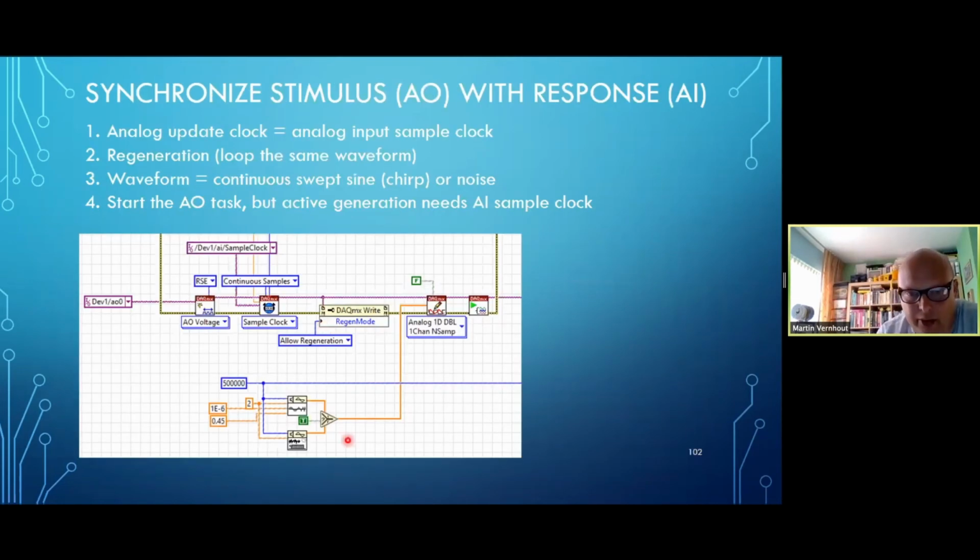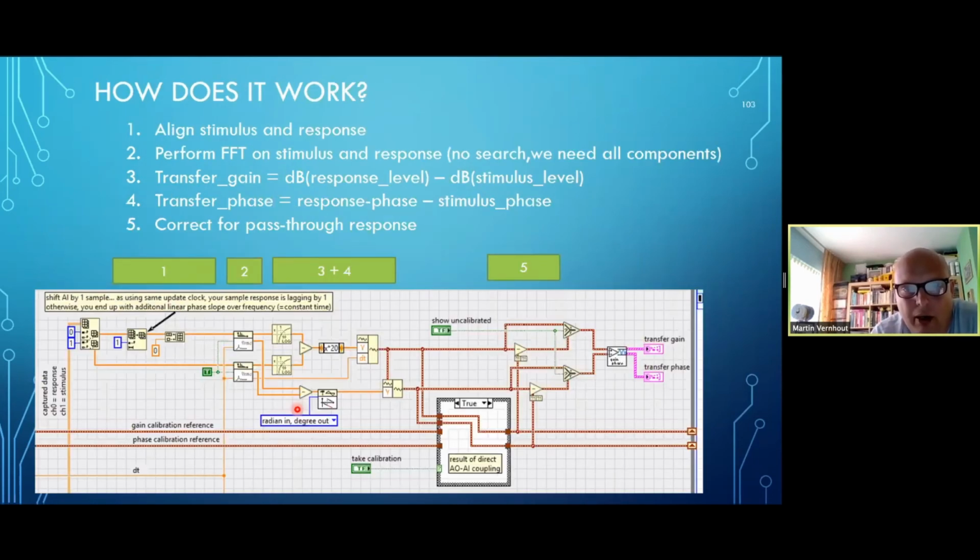Over here, we just generated it. It's a chirp VI coming from the signal generation palette. So it's fairly cheap. I think it's always present. Our analysis doesn't need to find a frequency because all the frequencies are actually valid. We just calculate the FFT.